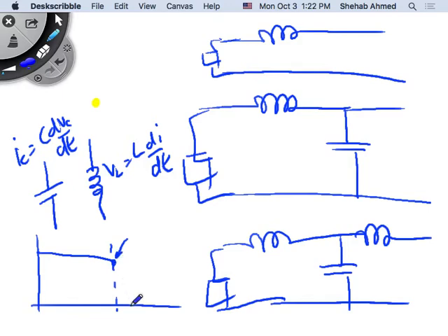And then from here, you're attenuating. For example, this is a gain of 1 dB. This is a gain of, I don't know, 40 dB or whatever, some gain corresponding to a certain magnitude in real numbers without dB. And then you're trying to attenuate everything else, right? So you're trying to attenuate the signal.